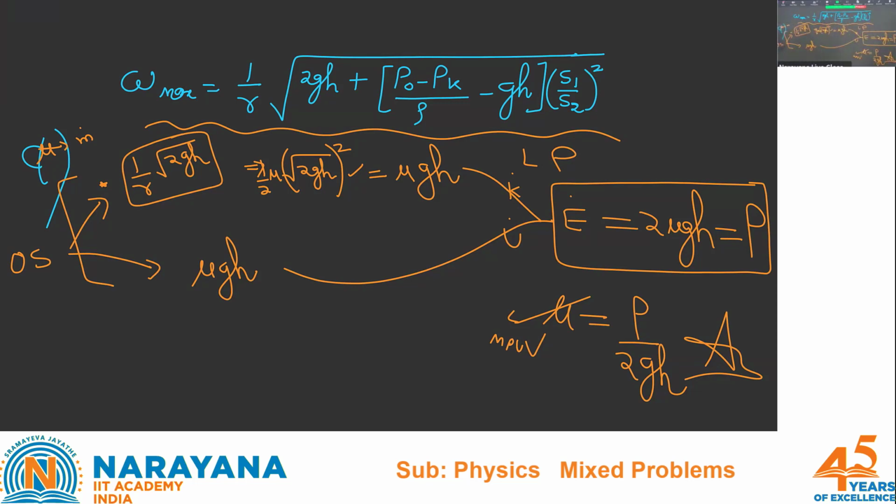मतलब pump मेरा चल जाए, this system just starts working. For that, I am trying to write the expression. So I just wanted to push liquid out without cavitation also, with no relative velocity, just fall off from it. But because of my omega, you'll get some r omega also. So no cavitation is happening.